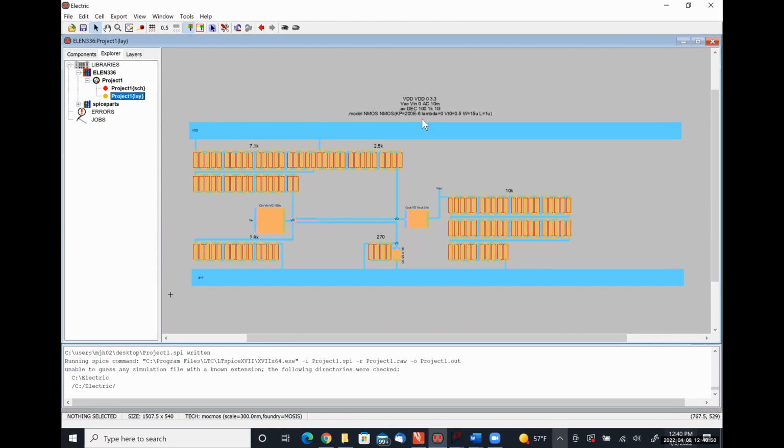Where I did take the time this morning to draw out each individual resistor and all that kind of good stuff. So this guy over here in the top left-hand corner is a 7.1K resistor. Each of these blocks of 5 is a 1 kilo ohm resistor wired into the next. Each of them represents a 200 ohm chunk. They're all just the standard 40 by 10 high-res polysilicon thing. To get 0.1, I just put 2 of them in parallel, right?